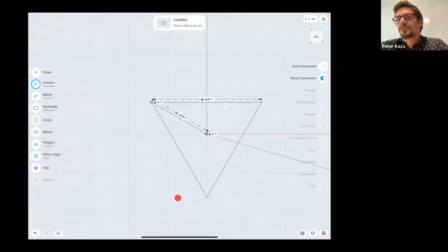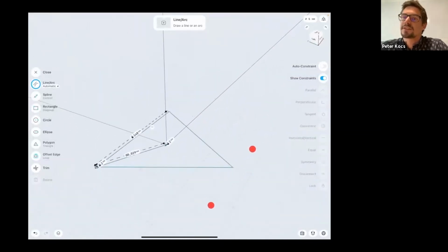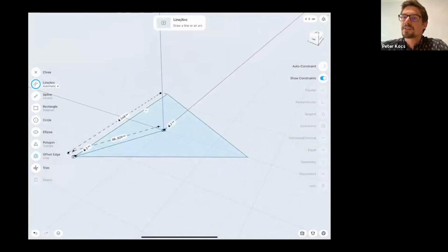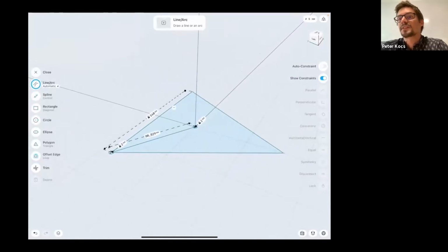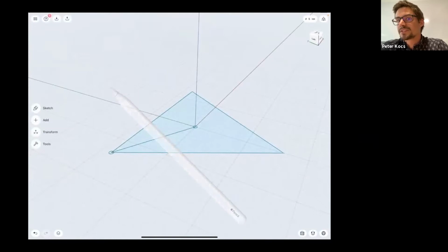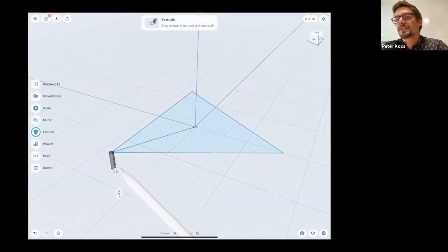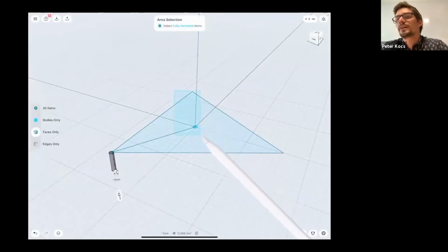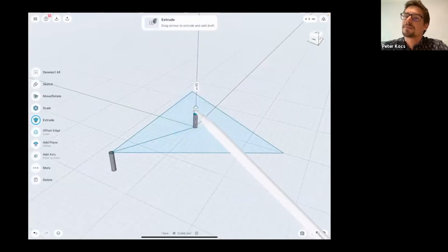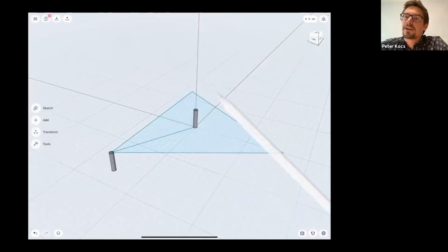After rotating away the view, you can see that the enclosed areas are highlighted with blue. That means you can interact with those cross sections. I will select the circle from the picker end and extrude it downwards by 18 mm. Then I'm going to select the vacuum inlet end and extrude it upwards by 18 mm. There I have the 2 vertical cross sections.